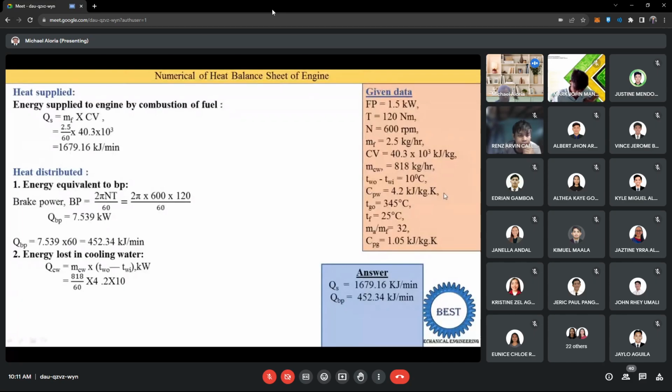So the answer is 572.6 kilojoule per minute. Here you see that the unit of mass is kg per minute, into Cp in kilojoule per kg Kelvin, and the temperature difference is also in Kelvin. So the Kelvin is cancelled and the kg is cancelled, then the remaining unit is kilojoule per minute. So we mention this in the answer.